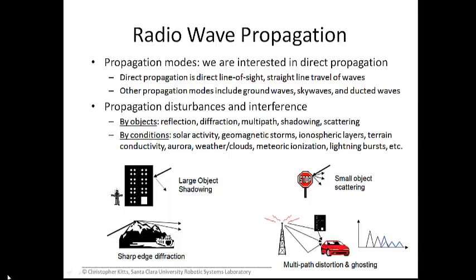And you can see in the lower right-hand corner there, we have a direct path from the antenna to our, in this case, car. But we also have paths that reflect off buildings or off the ground. And that results in receiving the signal multiple times. We get the first strong signal due to direct propagation, but we get a slightly delayed and weaker signal from what we call multipath effects, these other reflections and other ways for the wave to reach you, and that looks like noise to the communication system, and we want to be able to filter that out, ideally.